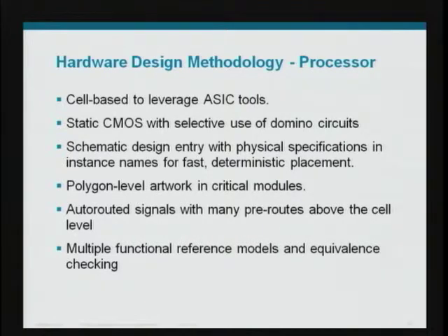And the reasons for this are numerous, but the most important ones are the advantages that you get in power by controlling wire lengths. Speed is another very important thing. Repeatability, particularly when you are close to the limit of the number of channels that your technology can support, wiring channels. Being able every time to get a consistent result by very carefully placing the gates is quite important. Our belief is that as we go further down into smaller and smaller technologies, this is going to be even more essential as the parasitics get even worse.